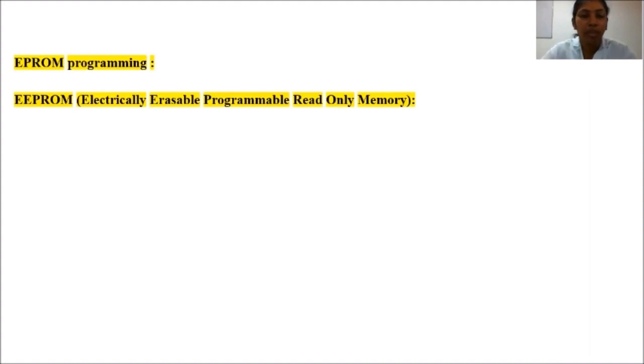So the programming in EPROM involves different processes. When an erased cell in the EPROM contains 1, data is introduced by selectively programming zeros into the desired bit location. Although only zeros will be programmed, both ones and zeros can be present in the data.